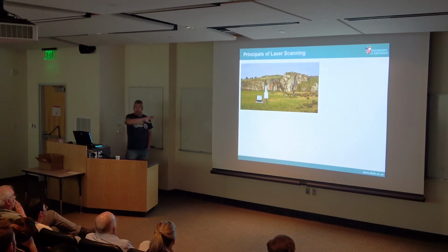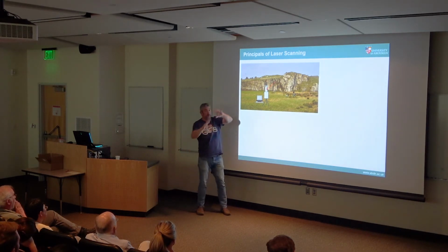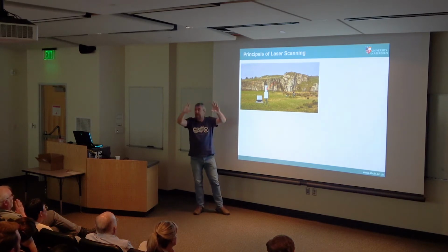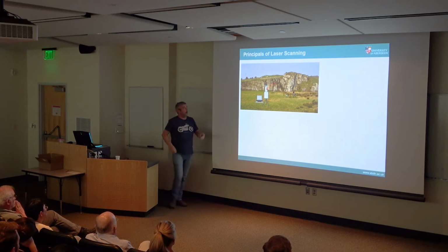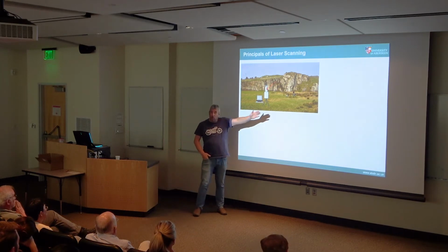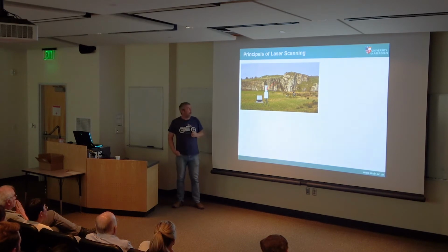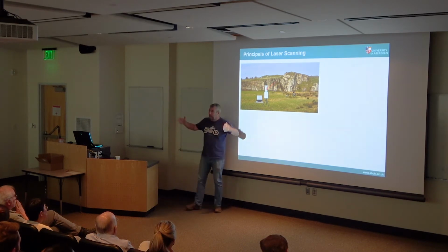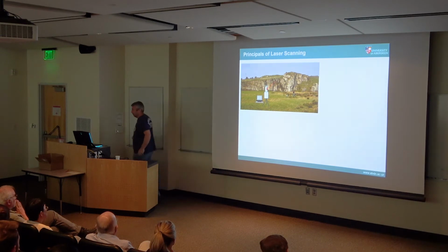And you build what's called a point cloud, and then from the point cloud you also take a bunch of photographs, and you create a surface, and then you drape those photographs onto that. And this was great. One scan for it to rotate all the way around took about an hour. You do about 10 or 12 scans a day, and the whole lot weighed about 160, 170 pounds, so we used to think it was relatively portable.